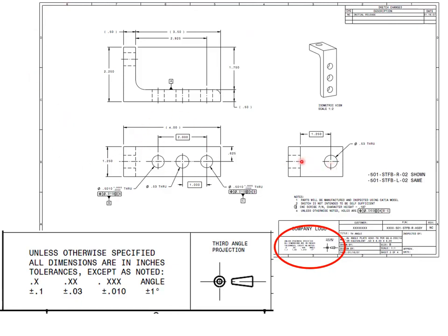So we have front view, side view, top view. One of the mistakes I see right off the bat is, notice how this leader is floating upward. I should have done the same thing with these other leaders here. Should have had them floating upward. And yes, it would have probably been crowded by these dimensions. So that's one excuse I can use.